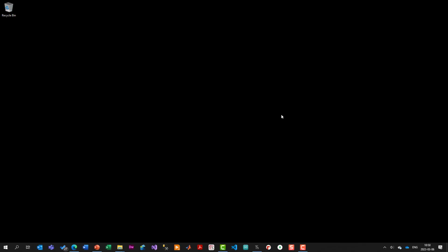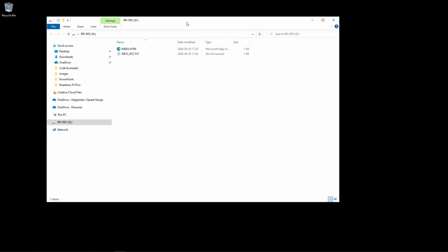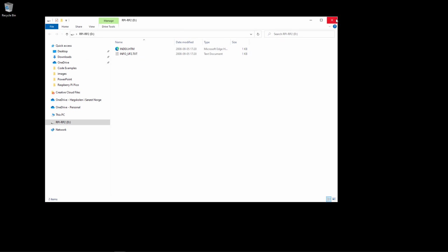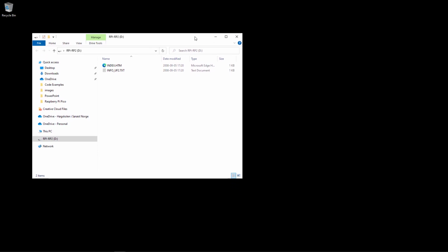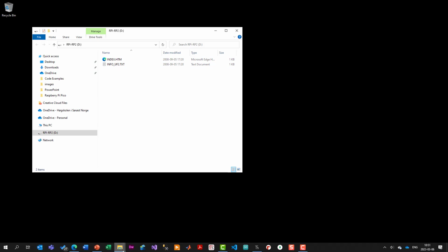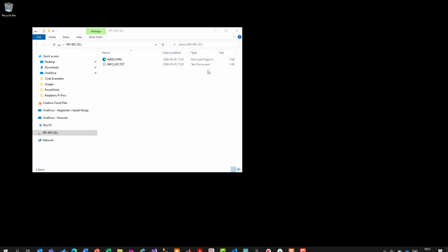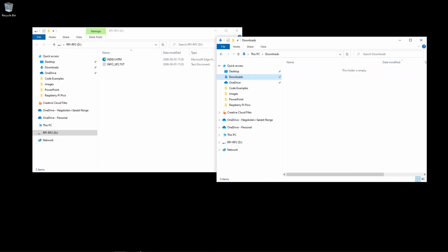So now let's see how we can install MicroPython on the Raspberry Pi Pico hardware. So then I can just hold the BOOTSEL button, connect the device using the USB cable to my computer, and this pops up. So basically, now in this mode, Raspberry Pi Pico simulates an ordinary USB device, basically a USB memory stick, and then you can download this MicroPython file. I have downloaded it here, and let's download it.